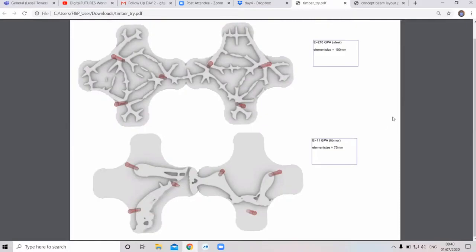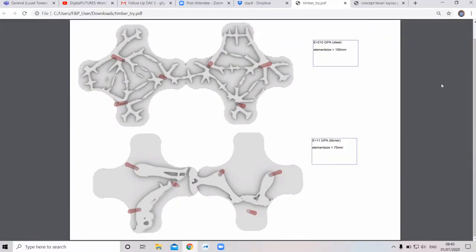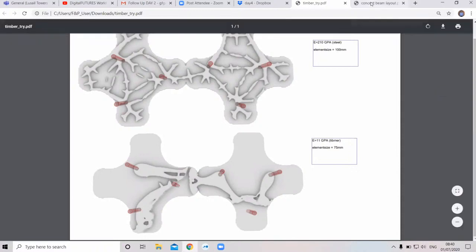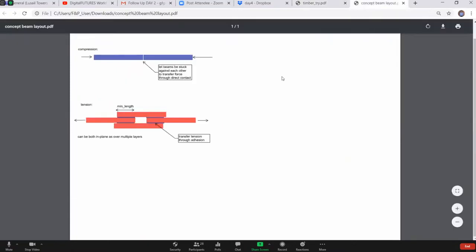There is some instability there, which is probably caused by the height of all the elements being too low, which will cause an unstable model. Because for timber, instead of a slab of 300, which we simulated now, you would probably have to simulate it with 500, 600, 700, 800 millimeters. Yeah, still curious if we can get it to work, but for now it's really something where I see: okay, let's just make it out of steel or something.